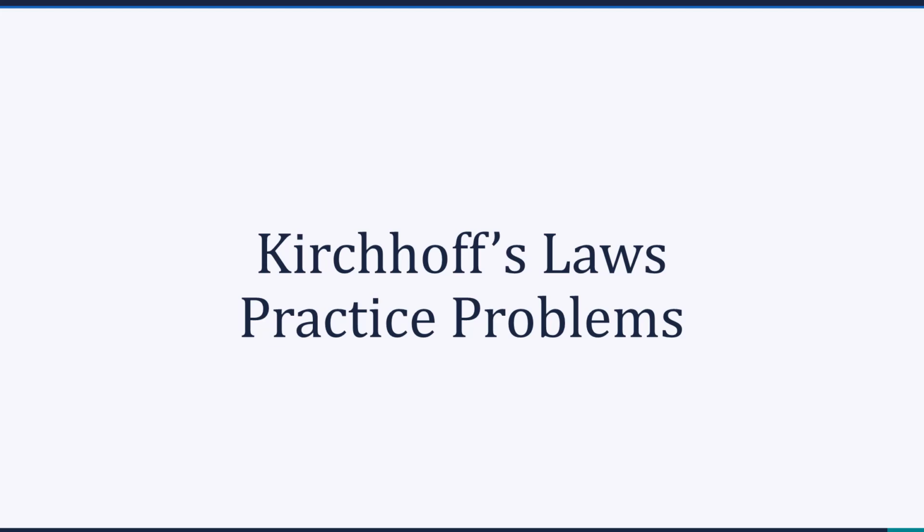Welcome, everyone. In this session, we are going to put Kirchhoff's laws to work by solving a series of practice problems. By now, you have learned the two foundational laws of circuit analysis, Kirchhoff's voltage law, or KVL, which states that the sum of voltages around any closed loop in a circuit is zero, and Kirchhoff's current law, or KCL, which states that the sum of currents entering a node equals the sum of currents leaving that node. We will combine these with Ohm's law to solve circuits step by step.